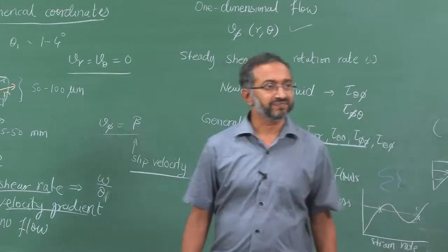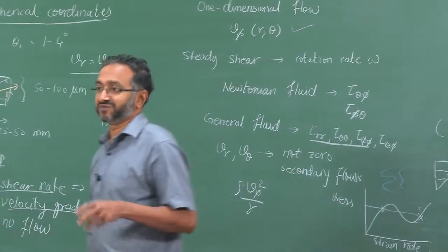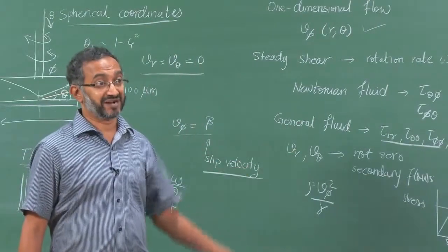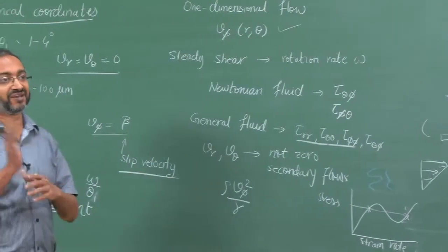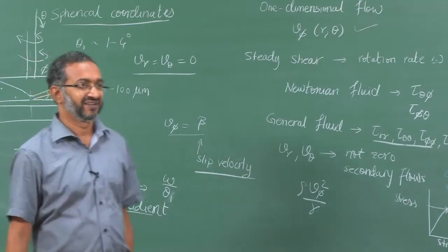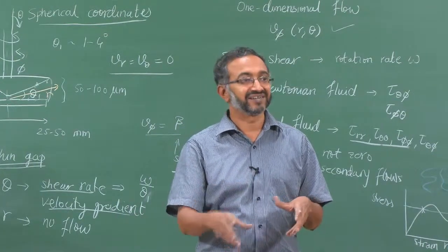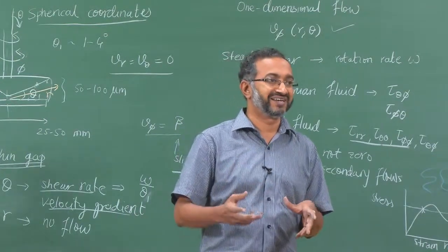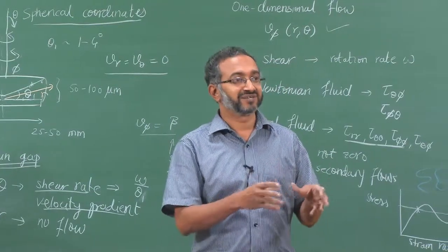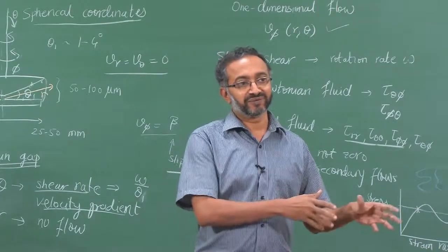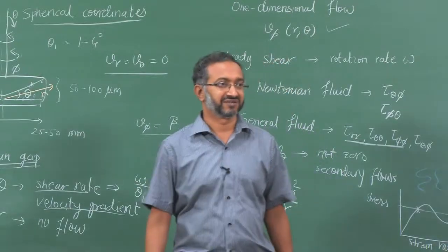With yield stress materials this is expected now, because some materials may not be yield stress and then still they will show shear banding. In case of yield stress, what you will see is no flow and flow. You will generally not see two different strain rates. So the feature in experiments, are you seeing it because of yield stress, the yielding phenomenon, or because of shear banding? Many of these are all mixed up, and unfortunately or fortunately many of the colloidal systems will show both. They may show shear banding and they may show yield stress also. So it is not always easy to say which one is the predominant feature.